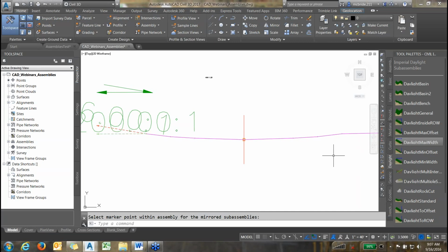Okay, so if you're familiar with the standard cross section, if you look at the standard drawing on this, the 412 standard, it'll have all this in here. It'll say half width is 1/4 of the depth, and 3/4 width is 1/2 of the depth. Those are all the spots we're supposed to be checking in the field. That's why I put those points in there, so it gets a more accurate parabolic shape. So with that, I think I'm pretty much done.